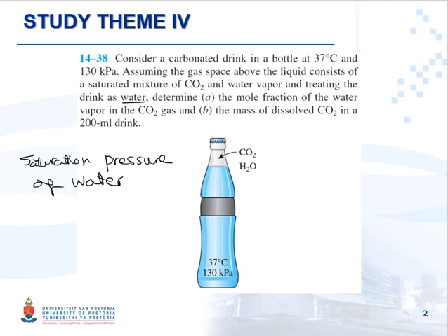So the saturation pressure of water at this temperature, 37 degrees, we need that one, so we go to table A9 and we read it, that the saturation pressure of water at 37 Celsius is 6.33 kilopascal.